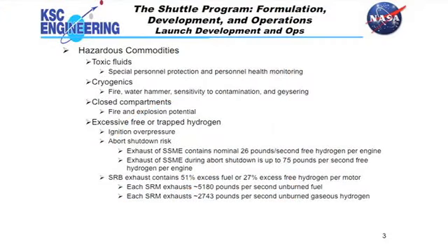Excessive free and trapped hydrogen. I think that it was mentioned ignition overpressure is a concern. We had a 6.4% model that was built in Huntsville to test these environments and to understand this overpressure, as well as to understand our acoustic environment, so we'd know how to design and what design to put in for acoustic suppression, or they call it sound suppression at the launch pad.